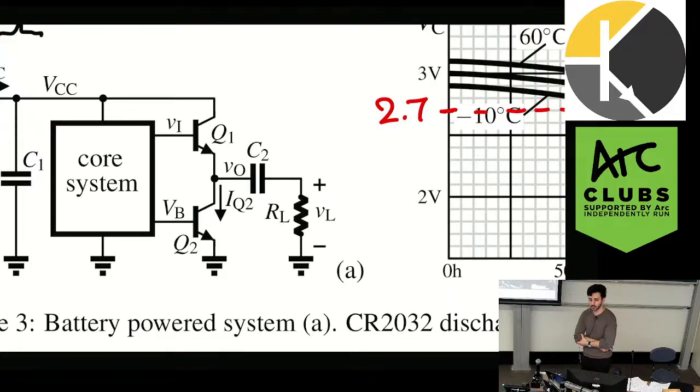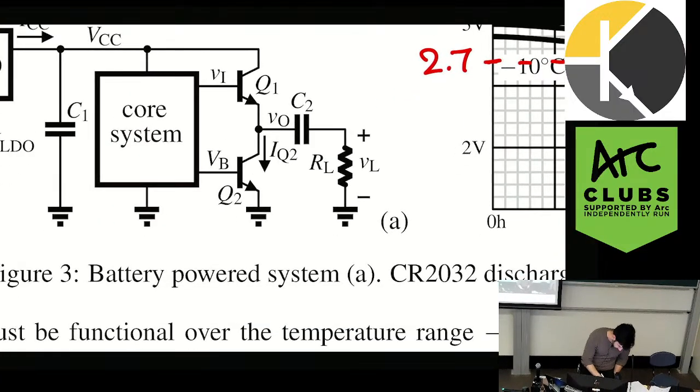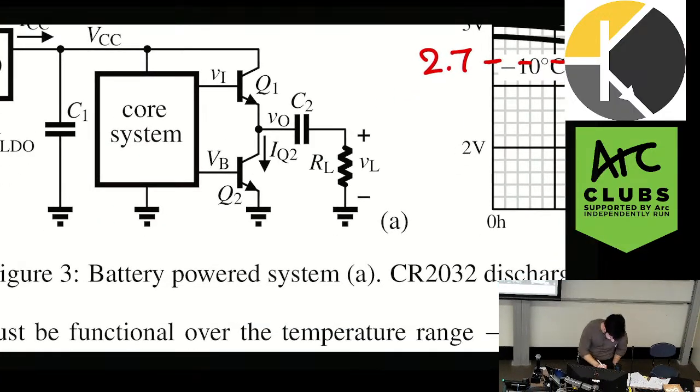And the question mentions that it's not acting in a push-pull configuration, because we know class A never goes negative, right? The input is always biased so that it stays positive, right? It never drops below 0. So it's not acting in a push-pull configuration. You can also tell because we have 2 NPN transistors. When you have a push-pull configuration, it's NPN, PNP. What that bottom transistor is doing is it's acting as a constant current source.